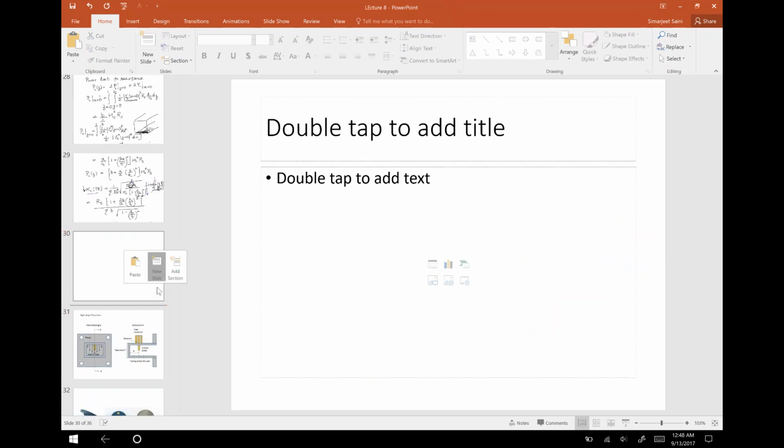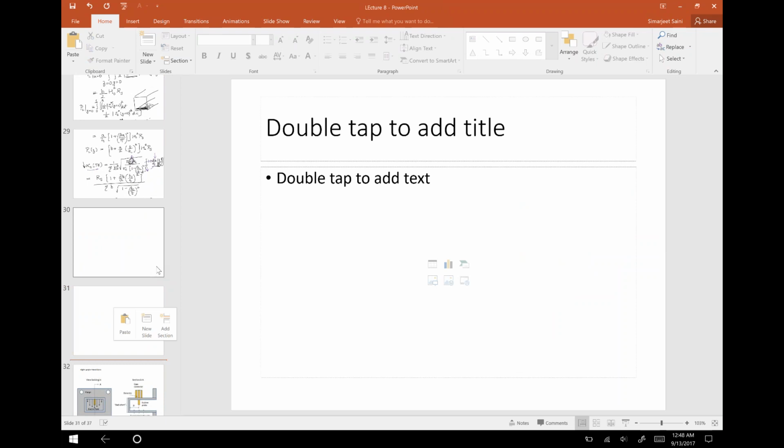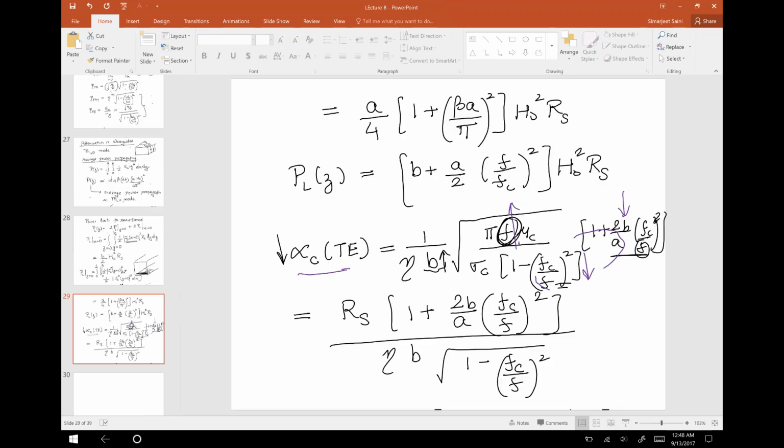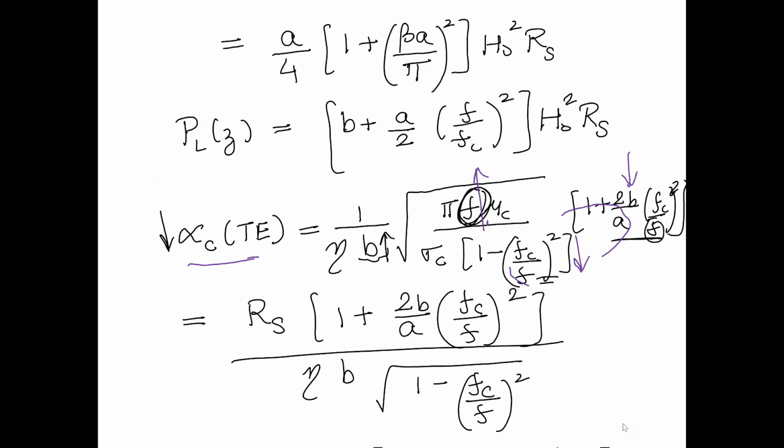Sir, you told that the TEM mode exists only when there is an inner conductor. So why are we not having inner conductors for rectangular or square waveguides? Or is the loss so much higher at these frequencies? Because the inner conductor is going to add loss too. So if I add the inner conductor in, the loss just becomes too much.